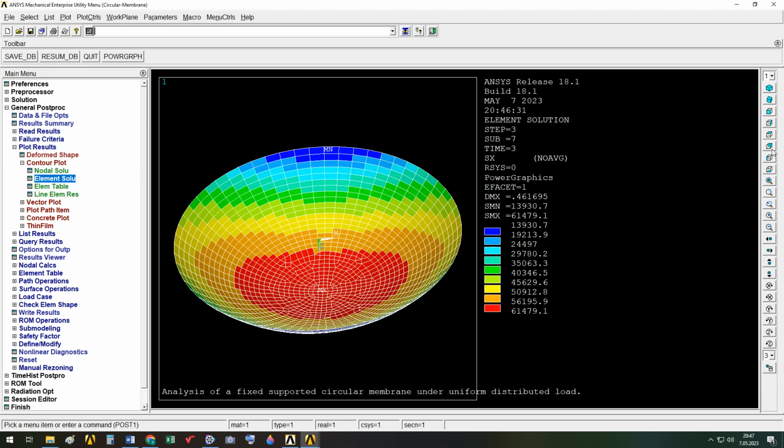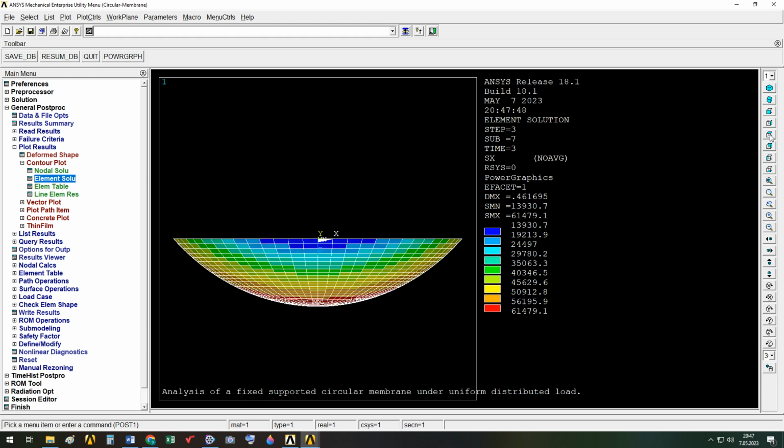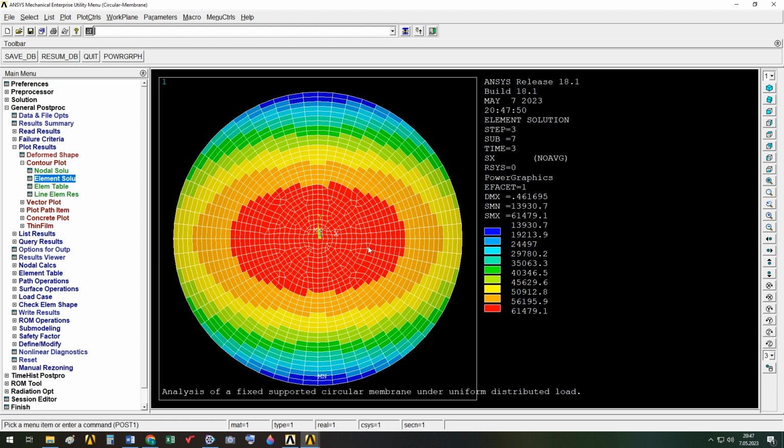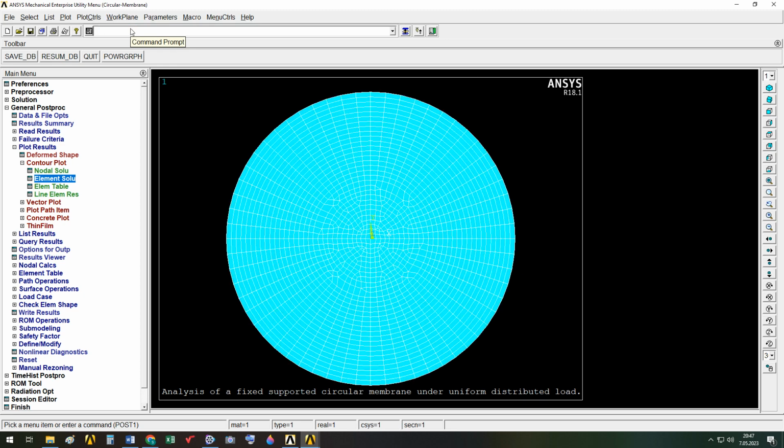To do this, first of all, using these commands here, top view, no, front view, okay. I will write here plot to see only the elements, and I will use this command to obtain the edge elements. Element select, new set by means of graphical picking.